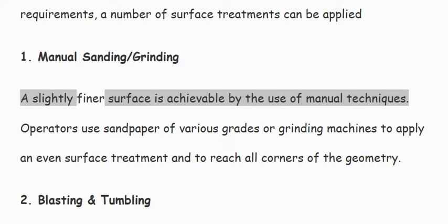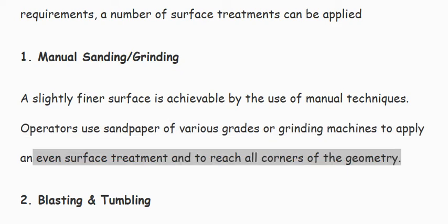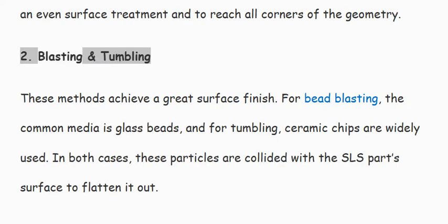A slightly finer surface is achievable by the use of manual techniques. Operators use sandpaper of various grades or grinding machines to apply an even surface treatment and to reach all corners of the geometry. 2. Blasting and tumbling.